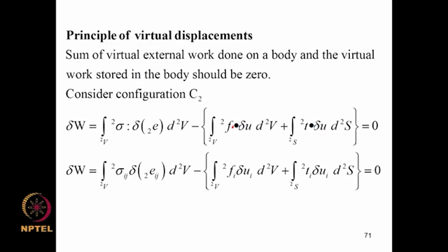The principle of virtual displacements was used to formulate the problems, and the problem was, if you use the Cauchy stress tensor and Eulerian strain tensor, which are both defined with respect to deformed geometry, we can set up the expression for the virtual work, but the problem is, as I already said, the deformed geometry would not be known. So, the volume over which we need to evaluate these integrals would not be known in advance. So, what we do is therefore introduce suitable strain and stress measures that help us to evaluate these integrals over known configurations.